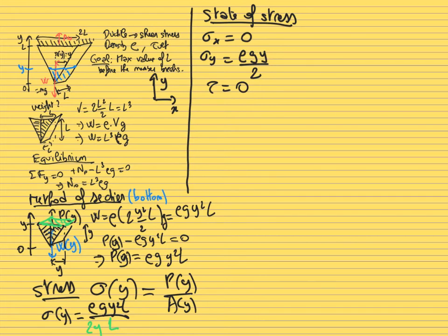But it doesn't mean that there is not going to be a shear stress in another direction than the axes x and y. So we need to draw a Mohr circle to find whether there is a direction where you have a shear stress. If so, what is the direction where the shear stress is maximum? Based on this, we will see at which condition this shear stress will eventually become larger than the ultimate shear stress that the material can sustain before it breaks.